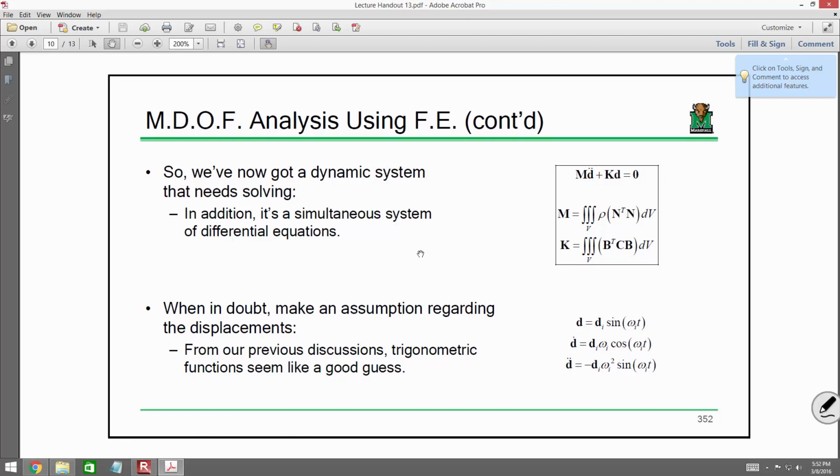Okay. Now, we've got this finite element system that we need to assess, and this is where the eigenvalue stuff comes into play, because we don't have just stiffness times displacement equals the forces, where we can just invert and that's it. We have to take a different approach. We say, well, all right, how do you solve a differential equation when the form gets kind of tricky?